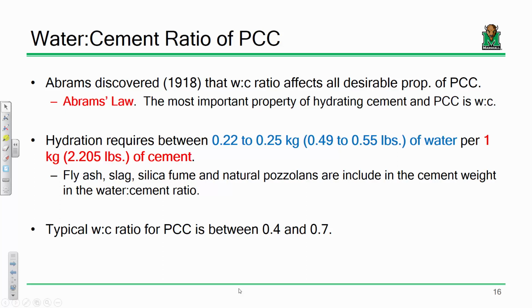What you'll find is that when we perform a mix design, and I'll just give you the overall philosophy with mix design, this is essentially how it works. What we're going to do is take 3 key pieces of information to proportion a mix. We're going to take our required compressive strength, how much compressive strength we want out of a given concrete mix. We're going to take its intended use.